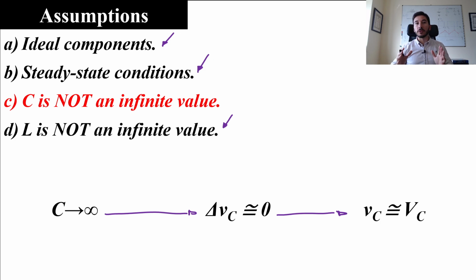In any case, I want to point out that this simplification is very close to the reality, because in the reality, when we do a DC to DC converter, we want to have a very constant output voltage. So we will choose the capacitance in a way that the ripple is negligible. Okay, so it's close to the reality, but today we cannot do this approximation because, as I said, the target is to evaluate the ripple in order to have a criteria to choose the capacitance.